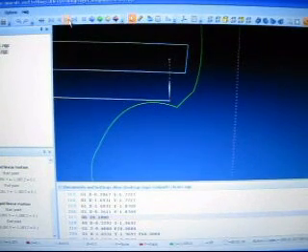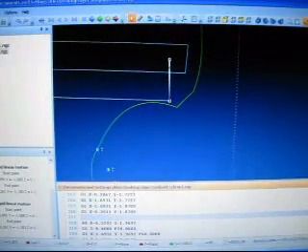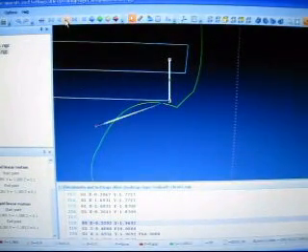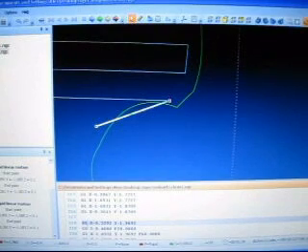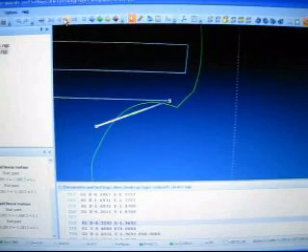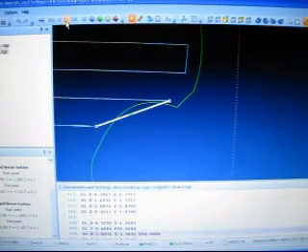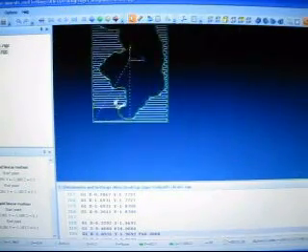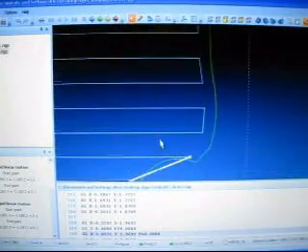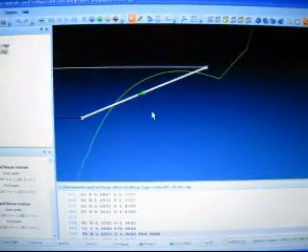So let me back this up, and we're going to go through this same procedure basically again. We're coming to this point, there's a rapid line. We're going to delete that rapid. Boom. Now it's going to go over here, but it's not feeding. So I'm going to change it from a G0, which is a rapid command, to a G1 to make it feed. And now I'm feeding right through his toe. So I've got to change my position. Let me set this for top orthographic view so we can see in more detail exactly how I want to modify this.